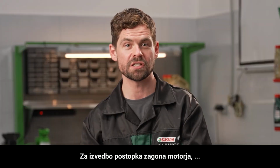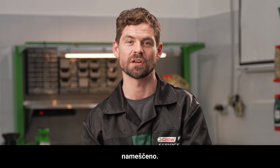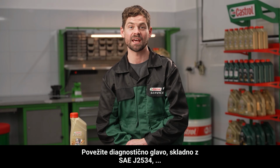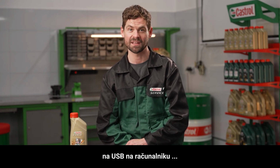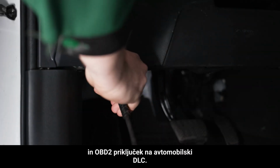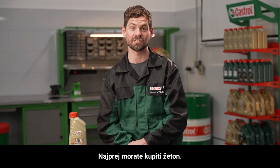To perform the engine start procedure, use a laptop with internet access and TechStream software installed. Connect an SAE J2534 compliant diagnostic head to the USB on the computer and an OBD2 connector to the car's DLC. Run the TechStream software. To start the diagnosis, first you need to buy a token.